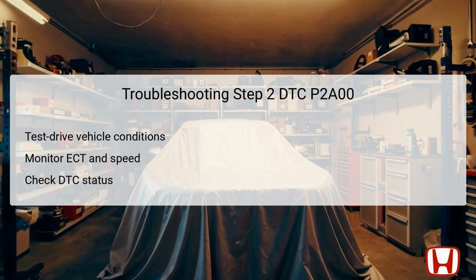During the drive, the vehicle should be operated in drive gear for CVT or in 4th or 5th gear for manual transmission, achieving a speed between 25 to 55 miles per hour, 40 to 90 kilometers per hour, for a duration of at least 5 minutes.